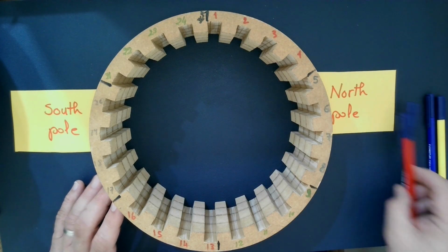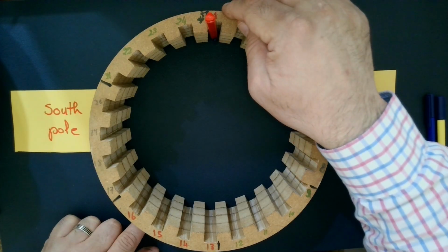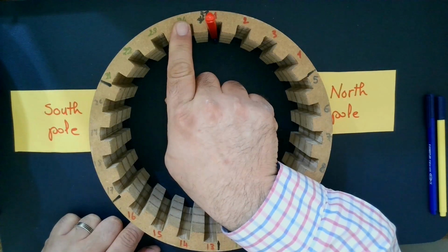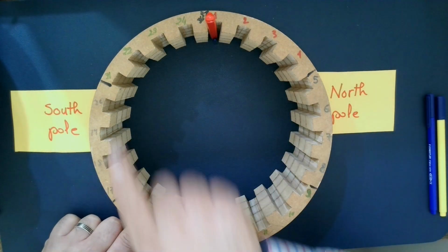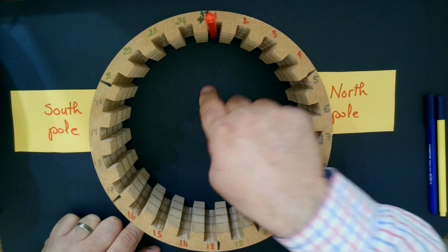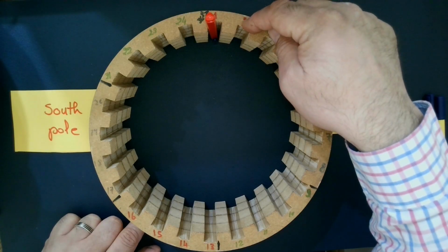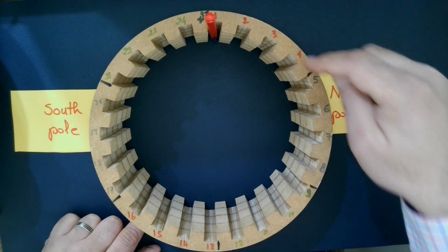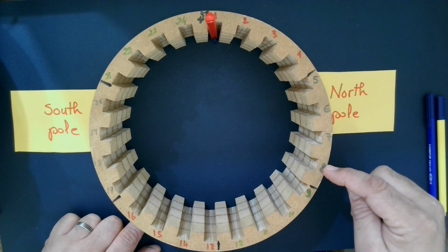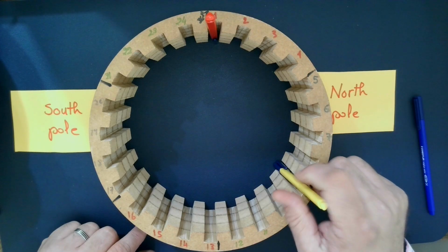So here I'm going to start by slot number 1. So this one is slot number 1. I'm going to start phase A. But we have 24 slots here. We have 360 degrees in the space. So the slot angle, that one will be 15 degrees. So that one is 15, 15, 15. So 15, 30, 45, 60, 75, 90, 105, 120. So we can start phase B at slot number 9.